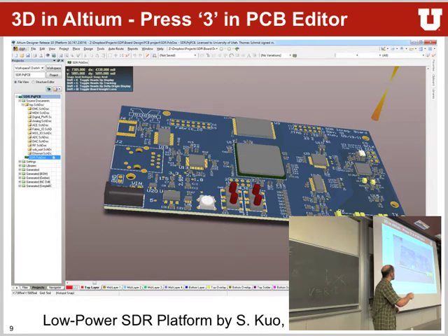This was a PCB designed by another student. It uses the same microcontroller we are studying, the SmartFusion here in the middle. And this is exactly the reason why we are not using the SmartFusion for your schematic designs. As you can see, it's a fairly complex architecture around it to lay out this board. This board has 6 different layers that go through everything. It's a BGA part, so nothing that you can hand assemble easily.